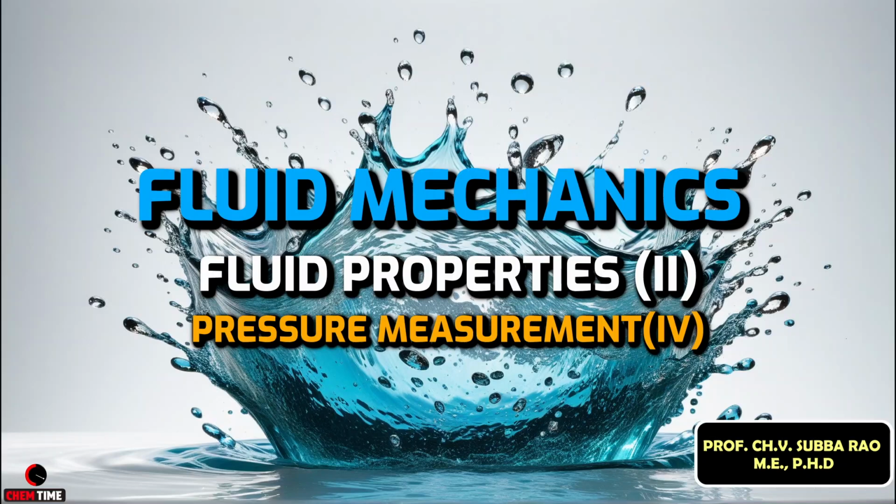Today's presentation will be discussing the use of multiple U-tube manometer for calculation of pressure or pressure difference. Now, in the last presentation, we have highlighted the limitations of U-tube manometer: the higher the pressure difference, the higher the height of liquid, and henceforth U-tube manometer cannot be used for measurement of high pressure differences. And in the literature, it has been mentioned that this problem can be overcome by connecting multiple U-tube manometer.